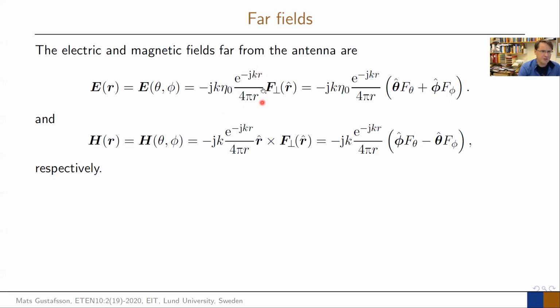And this says how the electric field then decays, and this is a scaling factor that stands in front of it. And that's just because we use the F here. And in many cases, we write that now in two new coordinates, which I will come back to very soon and say what they are. And that comes in from this case that they are perpendicular to this radial direction that goes away, which means that they will point in two other directions, which are on the tangents to those ones. So they're perpendicular to this radial direction. I call them here theta hat and phi hat. And I come back to those soon. And you see the magnetic field have the same shape, but with a minus sign instead.